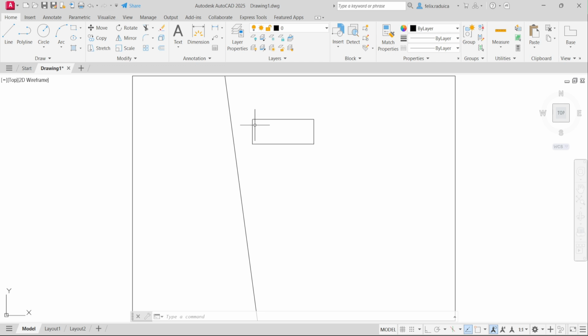So if I want a specific chamfer, this is usually done by giving two types of coordinates. Either you can give an angle and a dimension, or two dimensions.